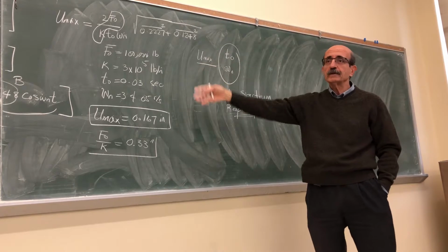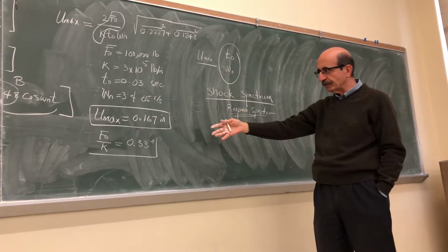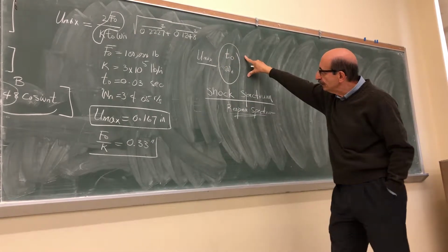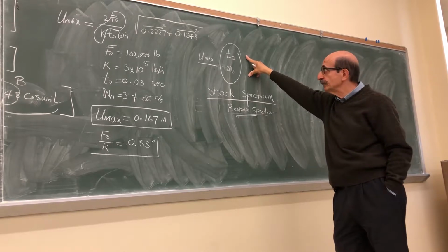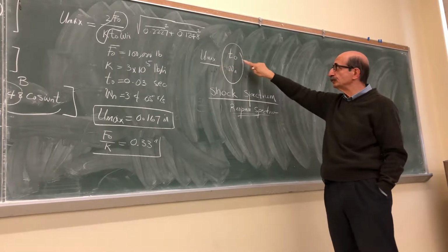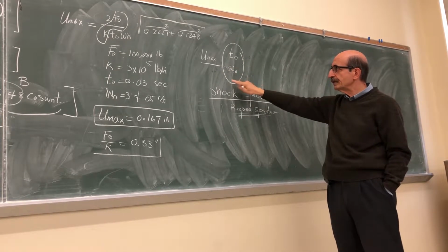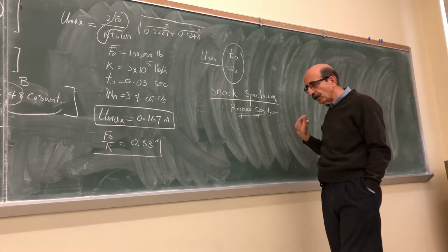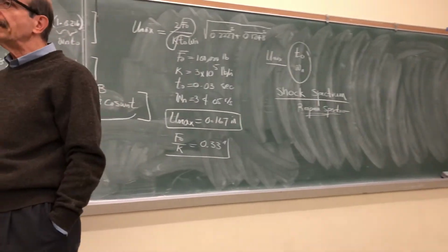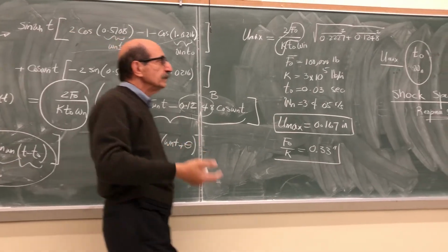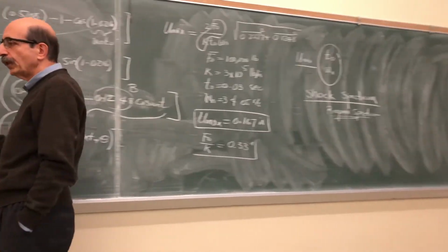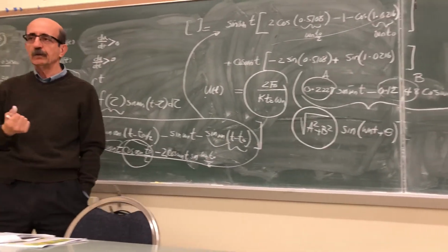But based on this observation, and realizing that the maximum displacement is really only a function of two variables, duration of the time and natural frequency, we introduce a concept which is called shock spectrum. In other words, in practice, the maximum displacement as a function of the time duration and the natural frequency of a system is plotted, and we'll study that, and we call that response spectrum.